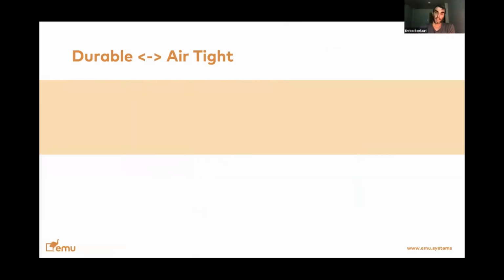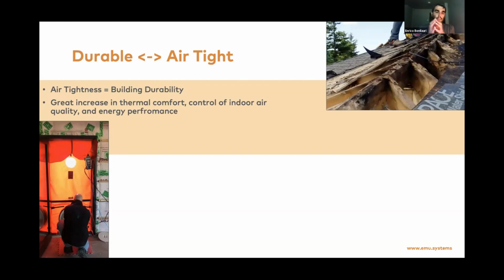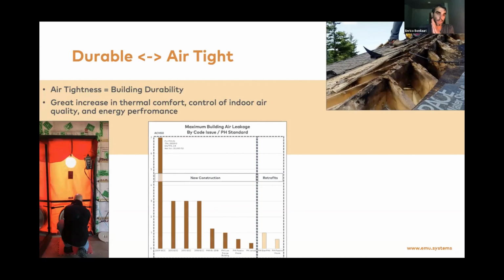As it does matter for durability inside buildings. Building airtightness equals durability. And this is something that we see a lot of fear and resistance from construction professionals in implementing, even just the bare code requirements for airtightness. This is something that has come along recently in building code. Starting from before 2012, you could have a very leaky building, where you could have as many as 7 air changes per hour at 50 Pascal, and you would still be compliant with code.